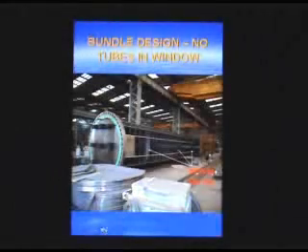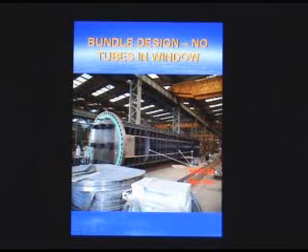Here's an example of a segmental baffle vertical cut, but it's a very special design because it's no tubes in window. You lose tube surface area, but you greatly reduce the risk of tube vibration because of your ability to put in intermediate support plates.